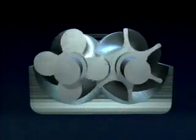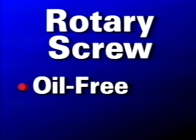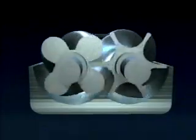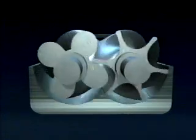In oil-free rotary compressors, no lubricant is used in compression, so the air is oil-free. This eliminates the need for an air-oil separation system. Dry and water-flooded rotary screw compressors are similar to the oil-flooded systems.